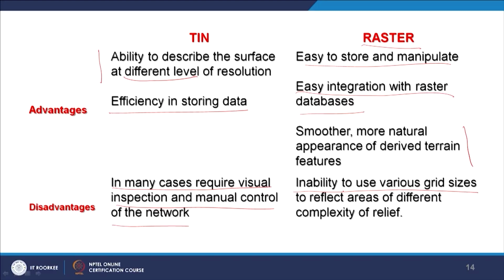Suppose I have point data and I create a TIN as well as a raster using the same point data. While creating the raster, I have to provide my resolution, and that is fixed for the entire file. Whereas in the case of TIN, I do not have to provide that information. When we see the demonstration, these points will come up again.